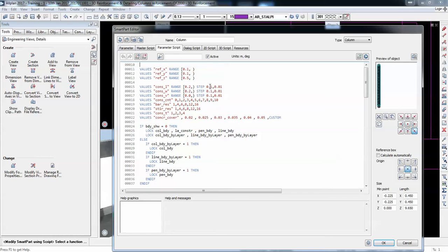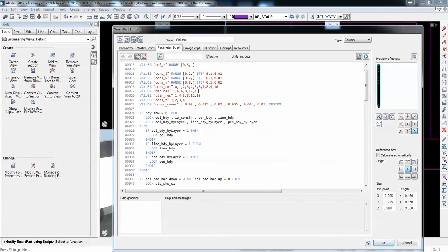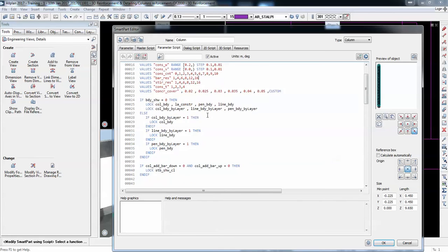So we don't draw millimetrically everything. So we draw something at multiples of 5 centimeters. And for each type of parameter, you get these values. You impose some values that the user can choose. So not to choose rebar diameters that are not available on the market.